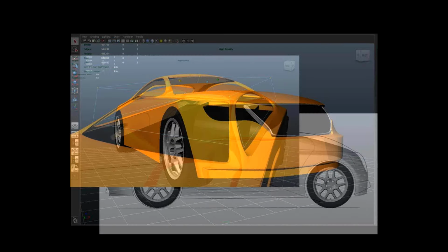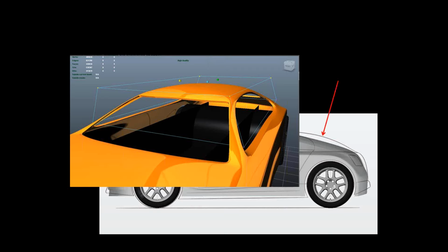This model then easily can be used for changes. For instance, with the red arrow here we can see there's a change in the center line, which is a dramatic change. It can be easily done in a polygon model. When I have to do this change in a NURBS model, oh my god, it would require a reasonable amount of time, really much.